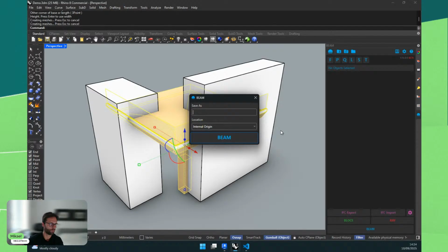And now we are in the export dialog. So first of all, location. Internal origin is, for us, the best workflow. You should have the internal origin of Revit and the internal origin of Rhino always matching. You should never model in world coordinates. It's always better to define a project origin, which is close to the geometry, always on the bottom left corner, so all the coordinates of the vertices and everything are always positive, right? So all these good practices should apply.